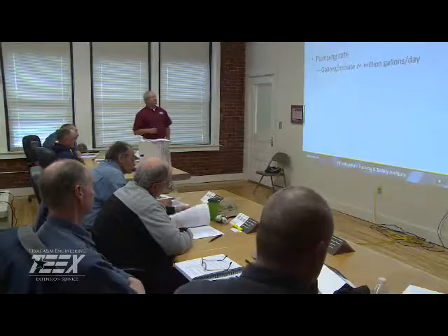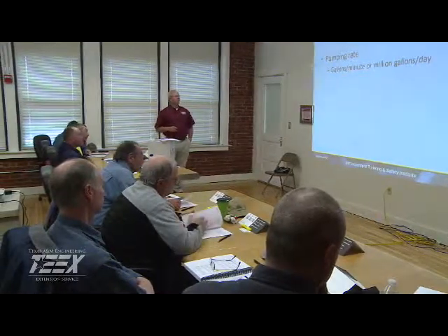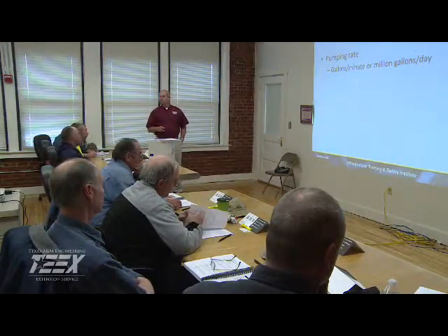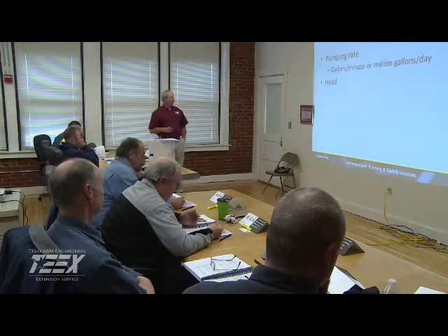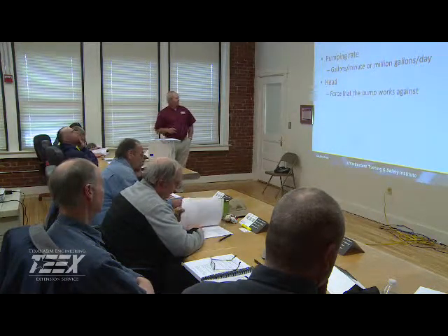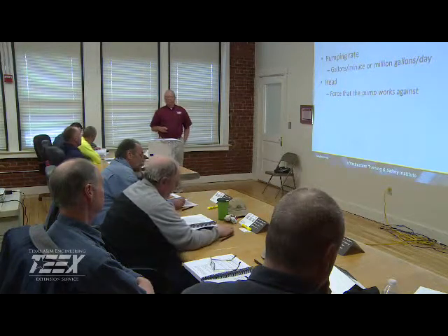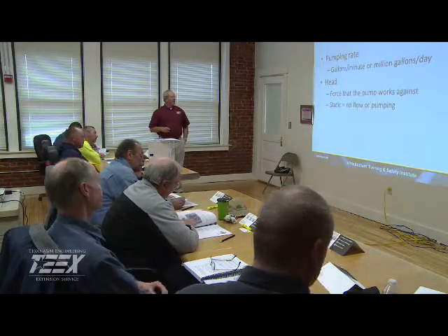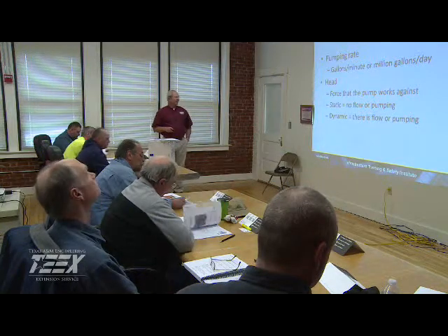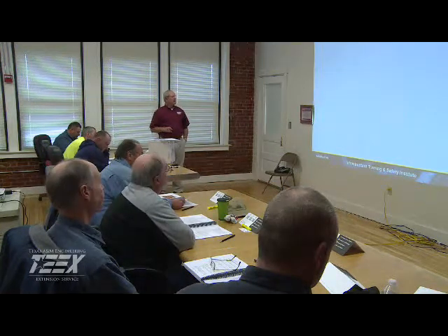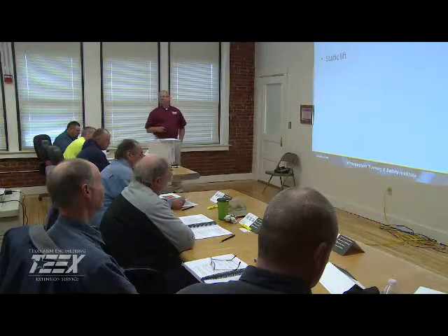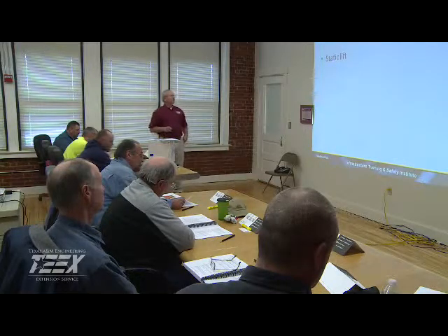Pumping rates, gallons per minute, or million gallons per day, or millions of gallons per day, it depends. Head, force that the pump works against. Remember, the highest elevation is what we have to overcome. Static, no flow. Dynamic is water moving in motion. And some of the static lift, we talked about that a little bit.